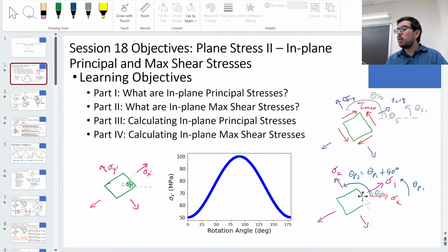Okay, so it might be a little bit confusing, right? Because we talked, even in pre-pro max, right? We had sigma 1 1, sigma 2 2, sigma 3 3. Those were to represent the x, y, and z directions. In this case, when we're talking about in-plane stresses, sigma 1 and sigma 2 usually refer to the principal stresses, which are the maximum, and often not in the same direction as sigma x and sigma y, as it was demonstrated here.